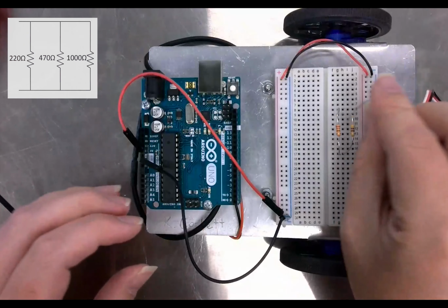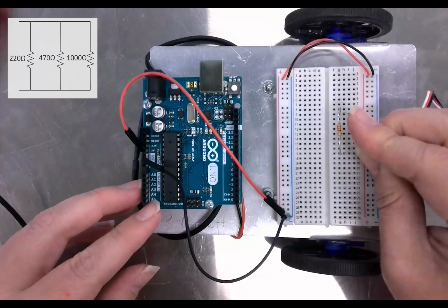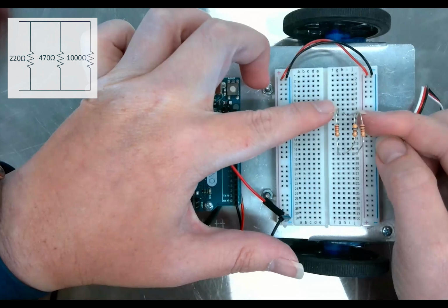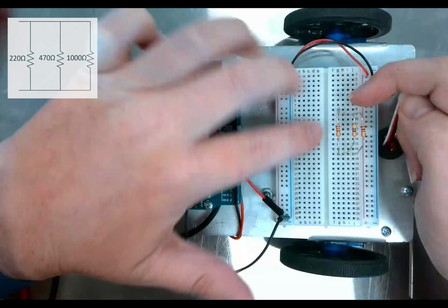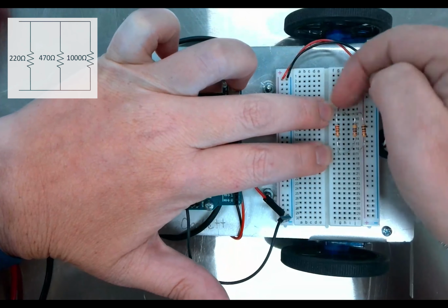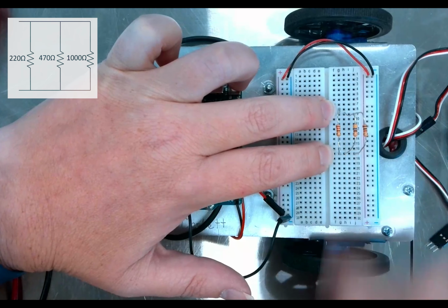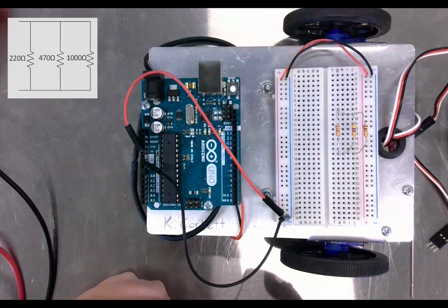And same thing with the 1000 ohm. So notice how I'm putting them all in right here, all the tops. Look how this matches the circuit diagram where you have the top row here. All of these, imagine if this was connected to positive and negative, all of these are connected, and then all of these are connected down here. So that's parallel. So I built these resistors to be in parallel with one another.